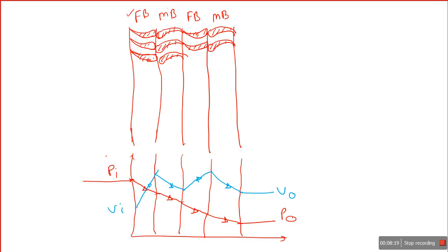But if you compare with the reaction, when the steam flows over the moving blade, there is also a drop in pressure because the cross sectional area between the blades is varying. In impulse the pressure is constant, but in reaction the pressure is also going to decrease because of the varying cross section. So the phrase varying cross sectional area between blades is very important. So I again conclude that in any moving blade, there is a drop in velocity.